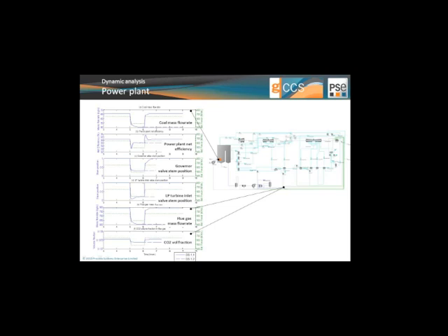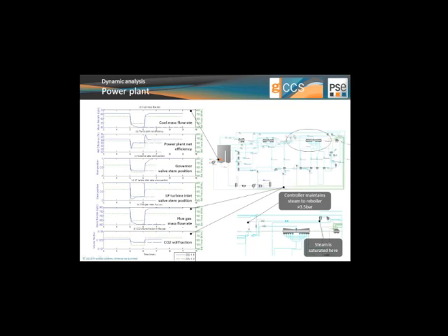If we observe the power plant net efficiency, we see that we have certain disturbances reflected, and that coincide with that 30-minute period that takes the power plant to settle back into a steady state. I think a rather interesting aspect to mention here is the LP turbine inlet valve stem position.